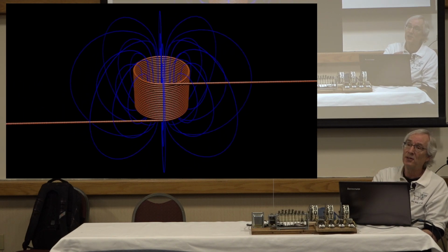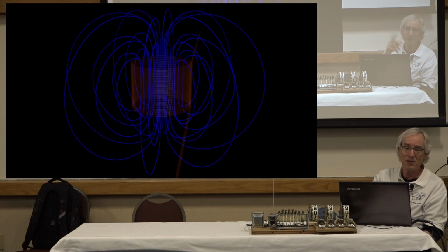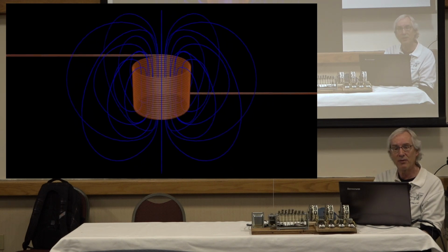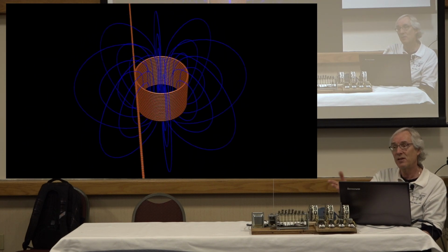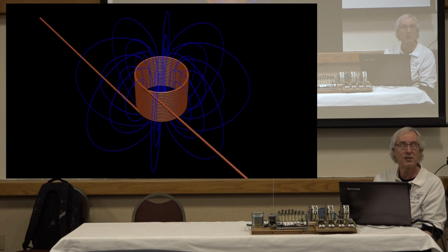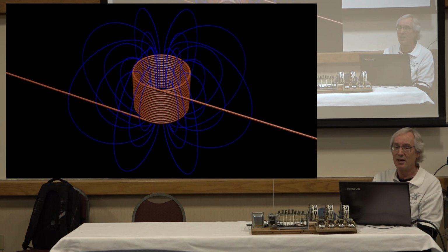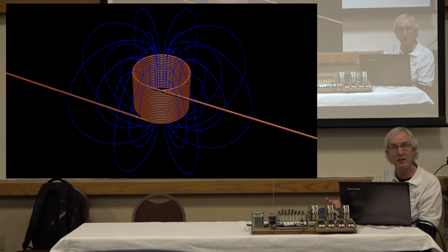So now this starts to look like the bargain magnet I showed you a minute ago, right? This is the magnetic field, and I can control it now by sending current through that or not sending current through that. And this is the basis of all of the electromechanical devices, all of the solenoids, the relay coils, anything that creates motion is created by this electromagnet, which has a magnetic field that I can create or make go away as I want to.